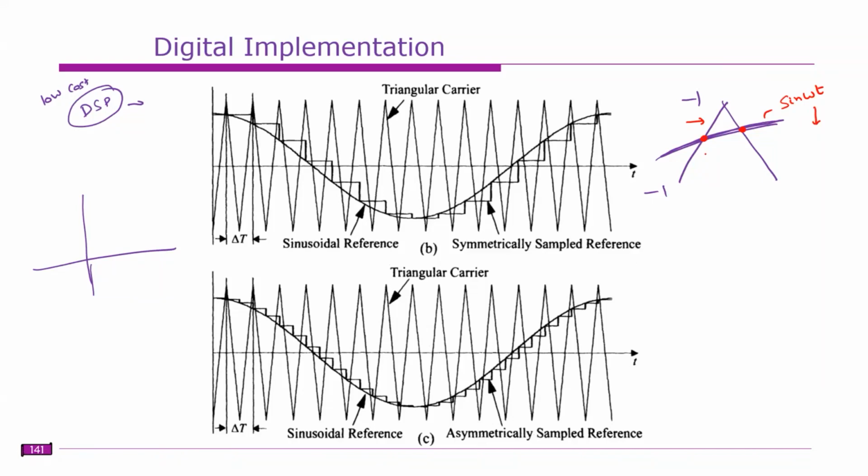So based on that, you can find out the intersecting points approximately. There is no exact solution to find the intersecting points of the sine wave and the triangle carrier, so you cannot obtain the exact one. One way is to discretize sine omega t by using the Taylor expansion. From that you can obtain the intersecting points, right? But those things are slightly complicated.